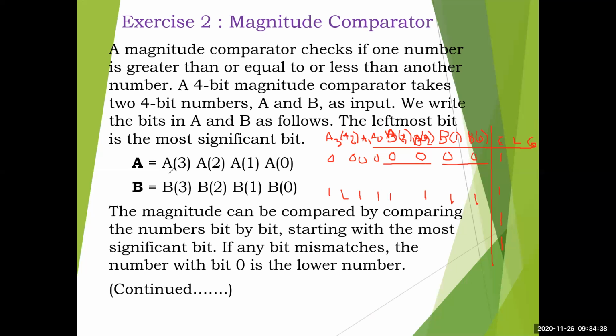So that is the complexity in data flow modeling. The same thing we will try to implement in behavioral modeling, that is the third style, or higher level of modeling, in Verilog HDL. So there we will do it in a very simple manner. We'll just use the relational operators, a less than b, a greater than b, or if else statements. Relational operators we could not use simply here, right? Along with that we require the behavioral constructs, that's why we could not do it here.